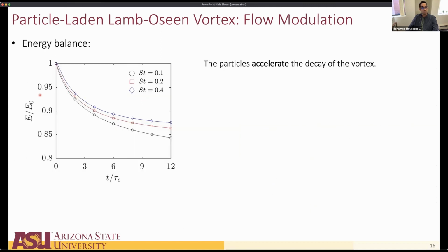Okay, so what does it mean for the kinetic energy of the fluid? Well, the kinetic energy of the fluid also drops significantly within this short time frame. One thing that's interesting is that the smaller particles, the 0.1 particles, lead to a larger drop of kinetic energy, but keep in mind that their clustering time scale is actually larger than the clustering time scale for smaller Stokes number particles.